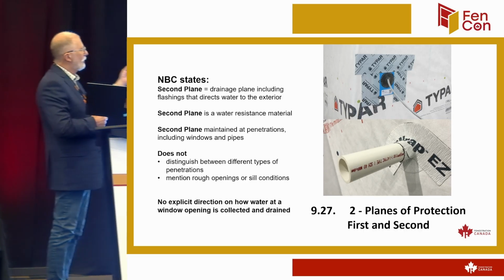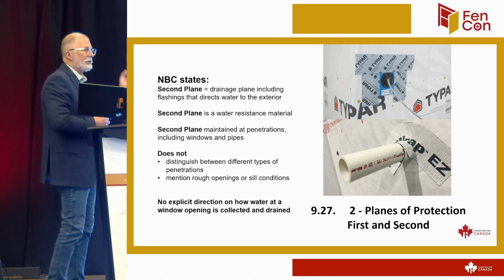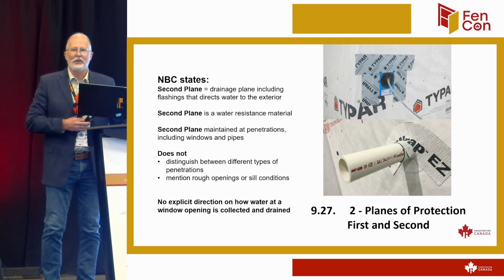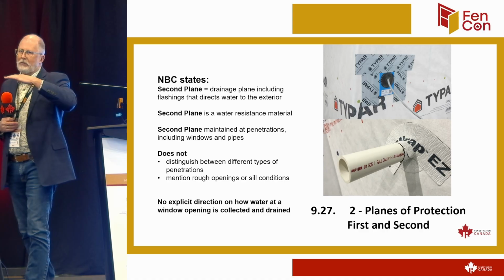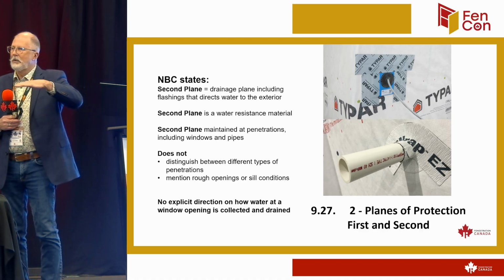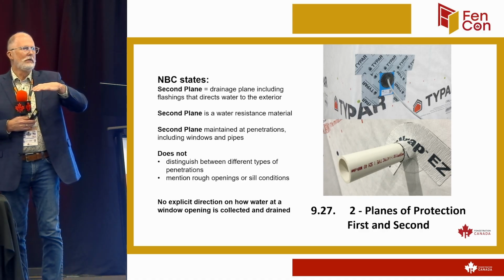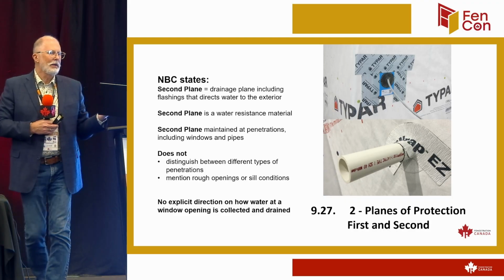Second plane is also a water-resistant material. We don't use the sheathing as second plane, and yet CSA says, hey, if you want to put that window in and you don't put any protection on the bottom, that's fine. So that doesn't really add up either.